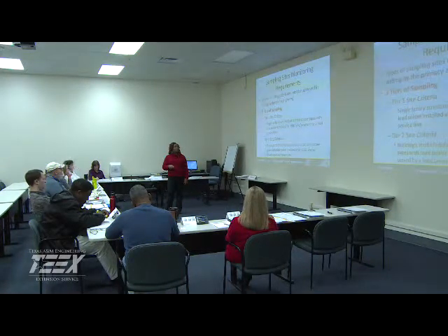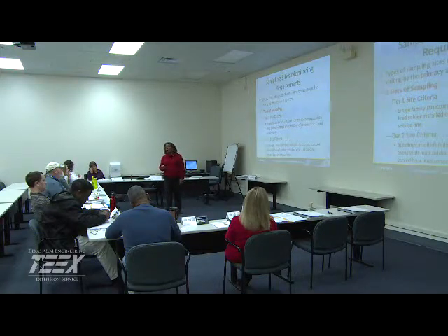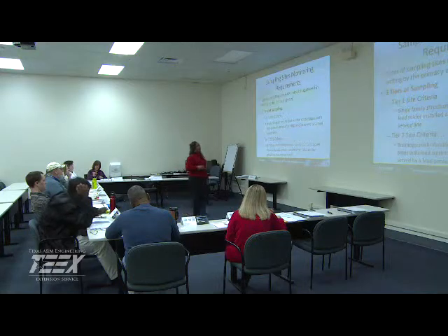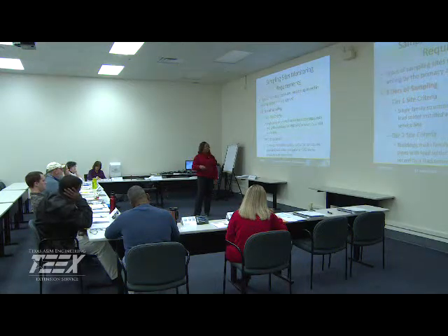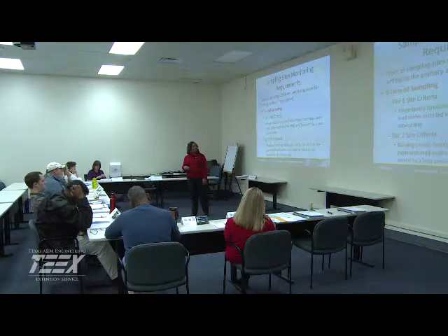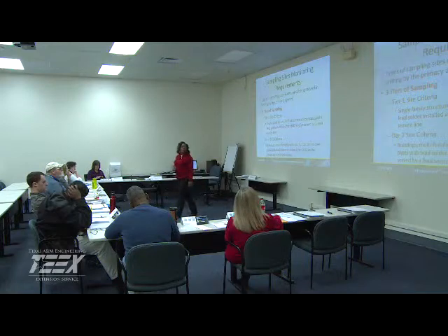Tier 1: single-family structures that contain copper pipes with lead solder installed after 1982 and may be serviced by a lead service line. Tier 2: buildings and multi-family structures that contain copper pipes installed after 1982 and/or are served by a lead service line.